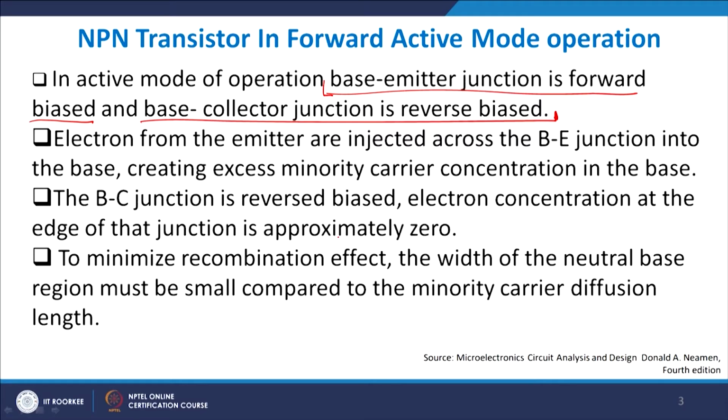Now, one important point which you should note as far as designing of a BJT is concerned, if you remember the previous talk, is that the IS value, the saturation current value, depends upon the cross sectional area of the emitter.